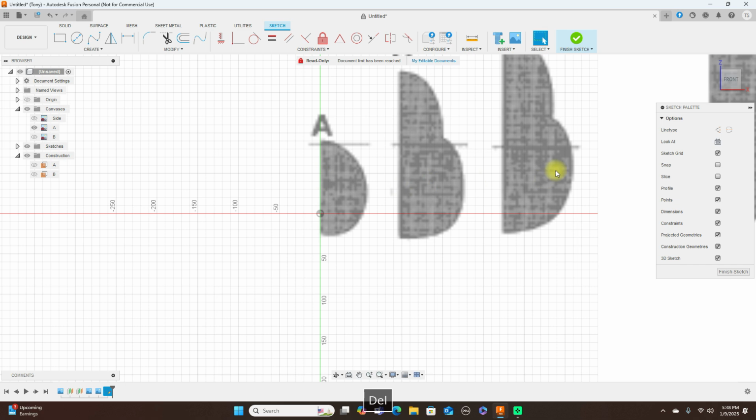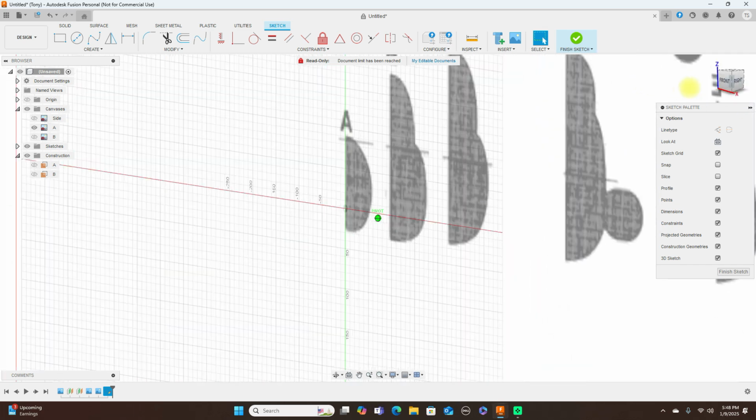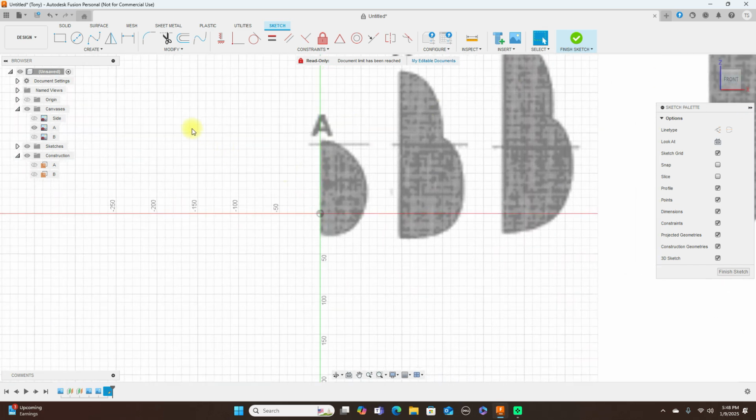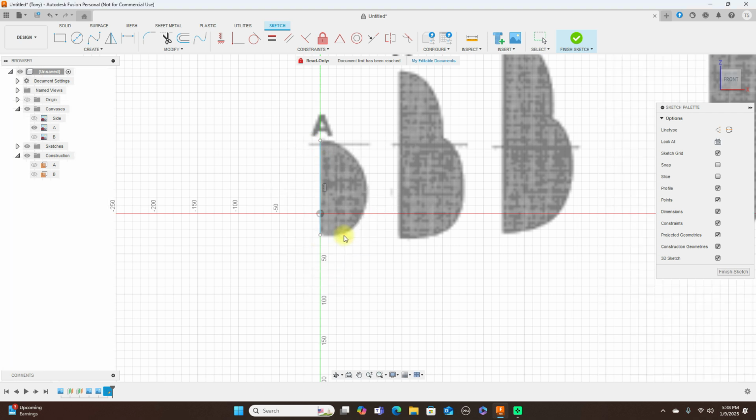Delete this. All right, and do that line again. It's the line command. Okay. Now, the fit point spline, like I was saying, you don't want to use a whole lot of points. So with this here, something like this, you can use 3 points, then move the handles around to get the shape.